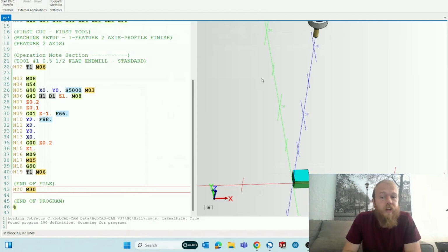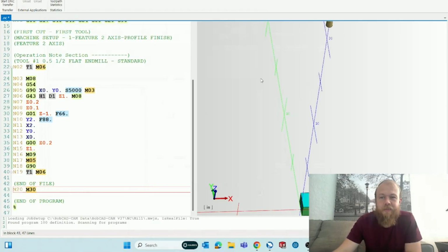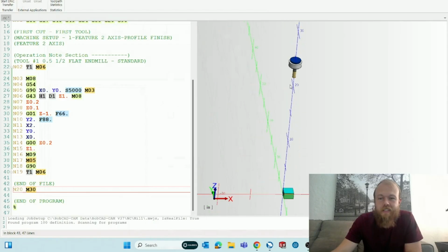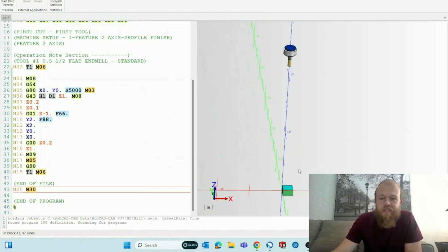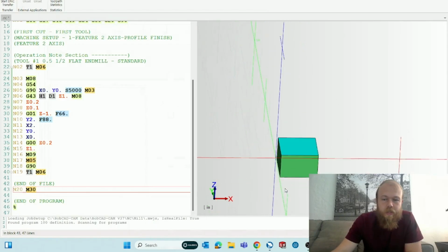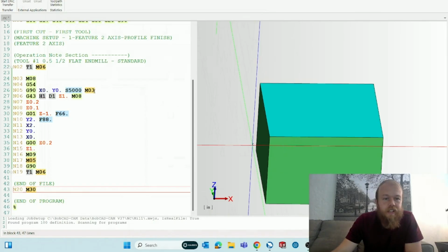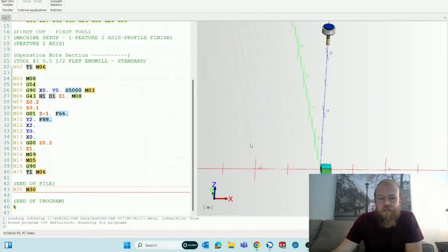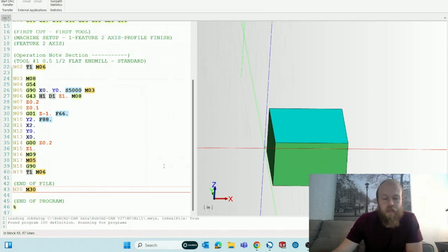I think it's a lot more user-friendly, looks a lot more advanced, a lot more sophisticated than our Predator software. It was pretty basic. This one's a lot more sophisticated, looks really nice, really smooth, and very easy to find what we're looking for. If there's any discrepancies in the G-code, like a bad Z callout, it's going to have a collision. It will give you the collision in the error reporting down at the bottom.